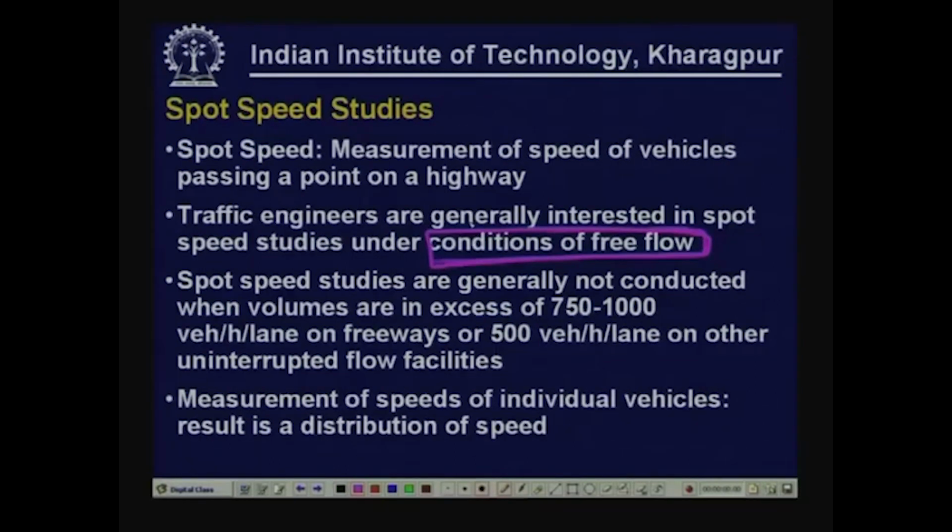If the road is under congestion, if the speed has already come down drastically, then there is no point in carrying out a spot speed study. So, traffic engineers are normally interested in spot speed studies when the traffic volume is not heavy, or rather the traffic is flowing nearly at a free flow condition.